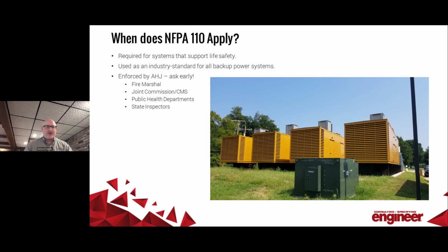So I get a common question of when do we need to apply NFPA 110? One way you can look at it is if it's for systems that support life safety, and that if the system fails, people could die. We're going to talk about what that means from a level classification here shortly.